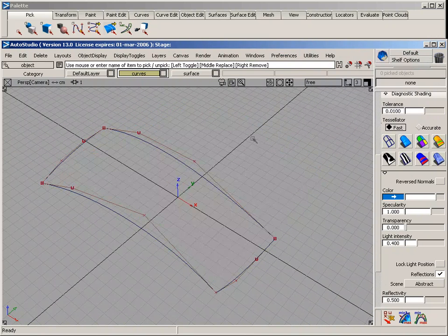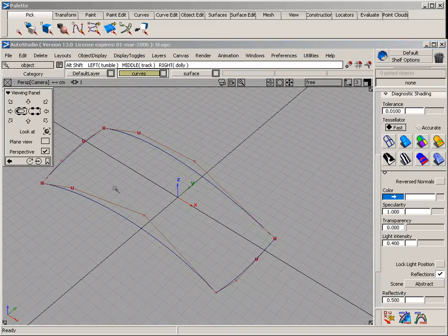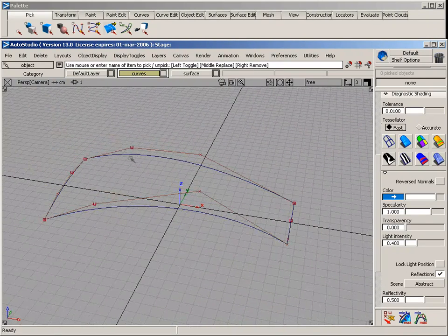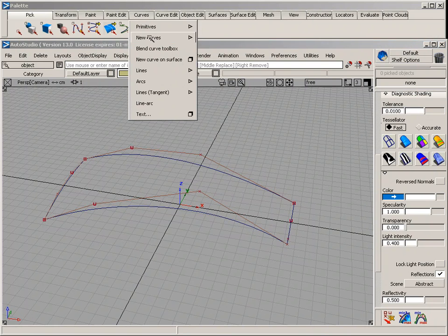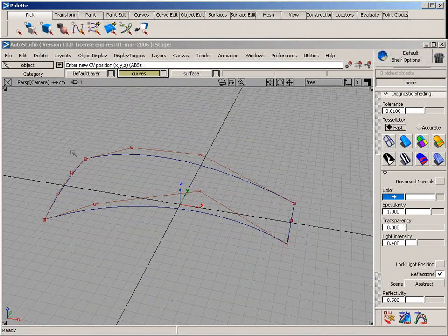For that, you can add additional generation curves in between. If you have a really complex shape, you could add multiple sections in here. However, for the sake of this demo, I'm just going to add 1 generation curve in between. Now, it's important that they touch the rails. So I'm using Alt-Control on the keyboard and then press to place the first CV.